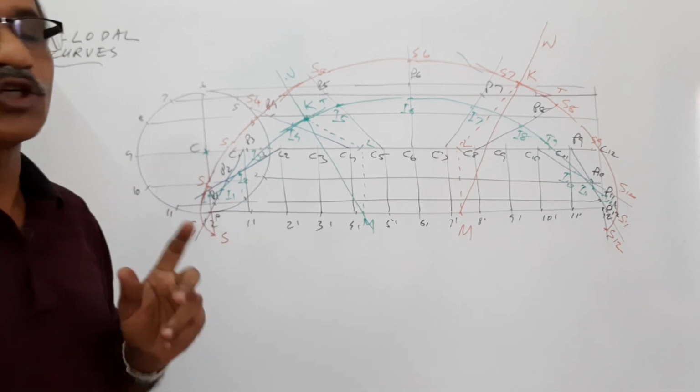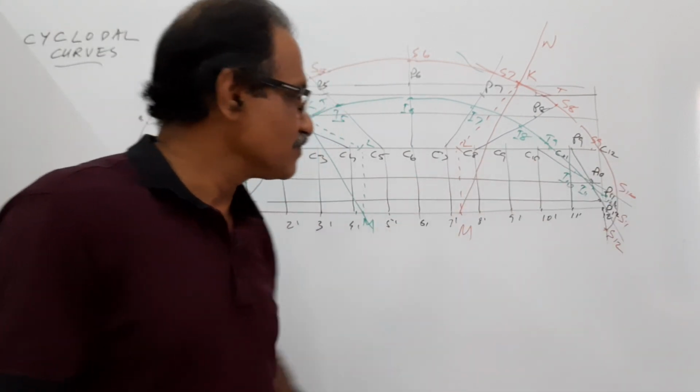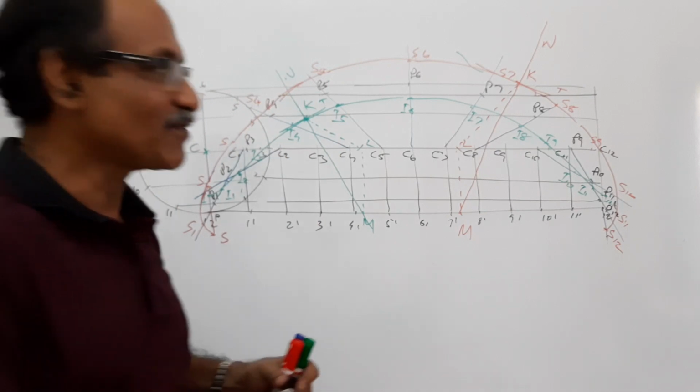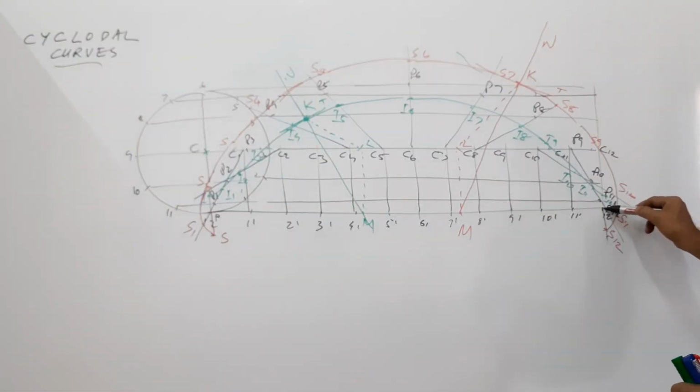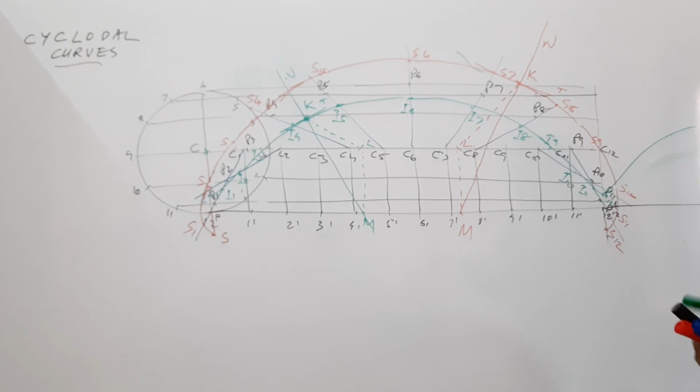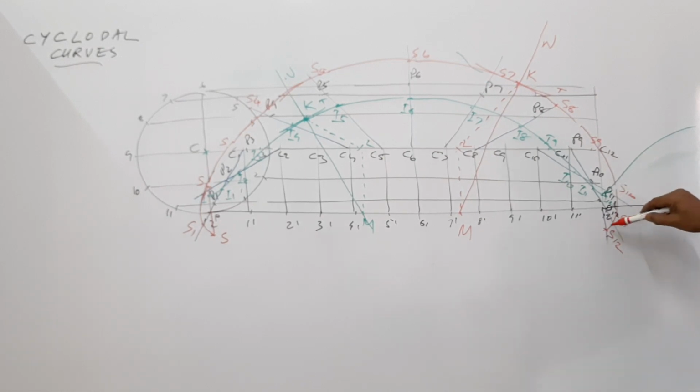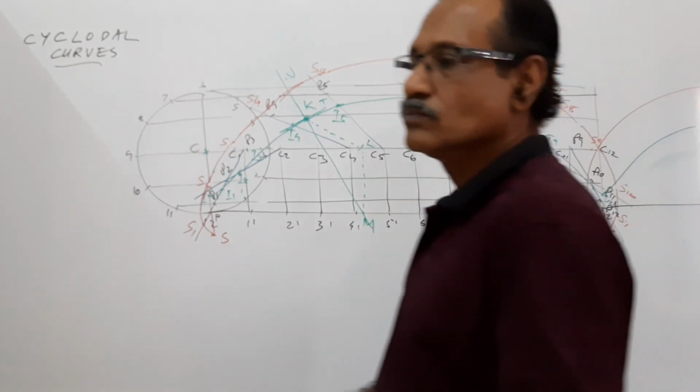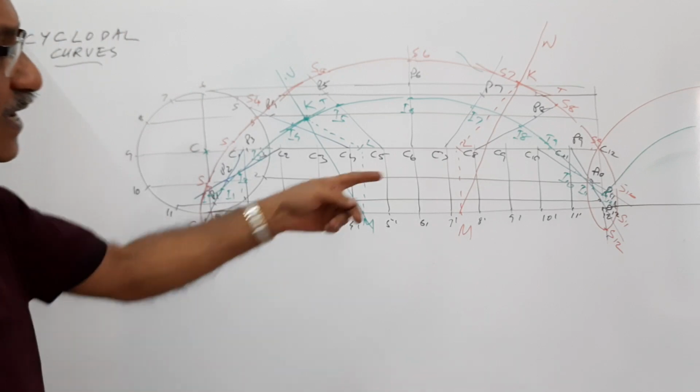In this case also, the circle can roll further. What happens? This is the line. If the inferior trochoid rolls further, what happens? It starts with a bend and goes like this. Just like the starting point, it starts with a bend and goes on like this. If the superior is repeated, what happens? It produces a loop here and goes like this. It produces a loop there and goes like this.